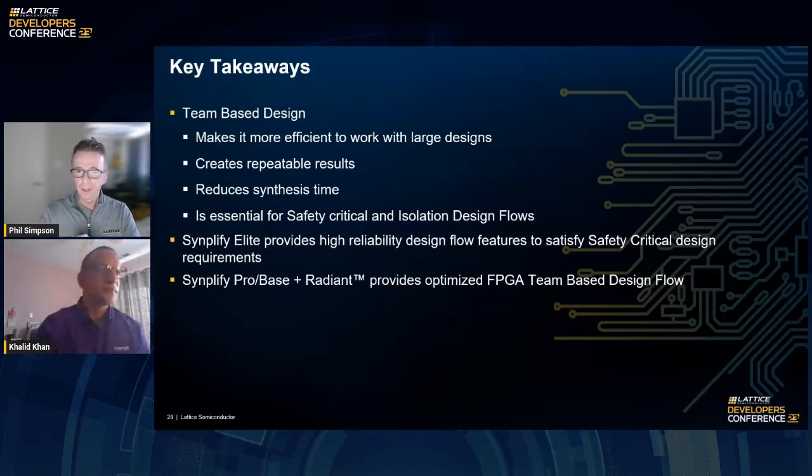Next question is, what level of granularity is available with the TMR feature? Yes, so as discussed on slide number 22, I believe, there are different types of TMR where you can do a local TMR, a register level TMR, or a block level TMR where you take the entire module block and triplicate it, or distributed TMR, which is more comprehensive, that does the internal logic of the block as well as the output of the block and serves the voter logic.